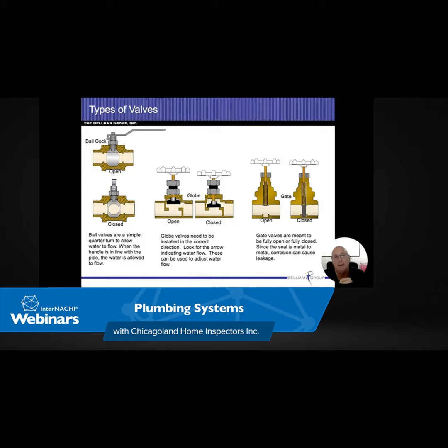So the dishwasher goes up, it comes over the top, we have the air gap, and then it goes back into the drain that goes into the wasteline. Typically around here, we're going to take our dishwasher and mount or secure it to the underside of the countertop. It's what we call a high loop. That's the common practice, not putting in one of these air gaps. Not saying there's anything wrong with it.